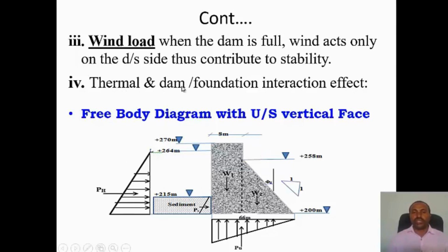So thermal and dam foundation interaction effect. This is the last one, the unusual load combination, which is secondary loads. Thermal: sometimes the temperature of the dam body may increase. That's why pre-cooling and post-cooling procedures are undertaken during construction.